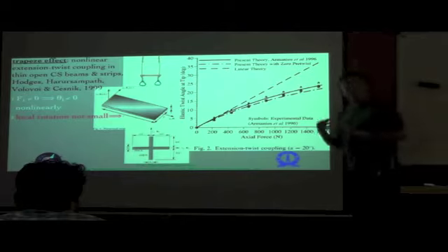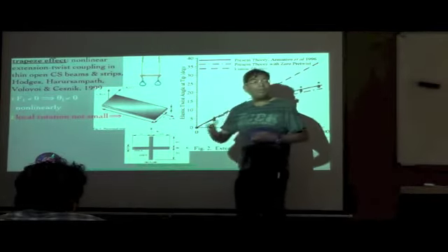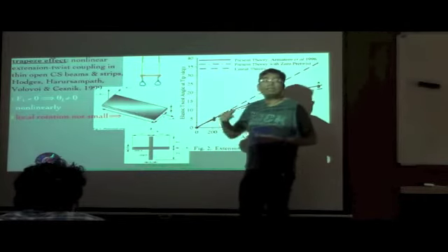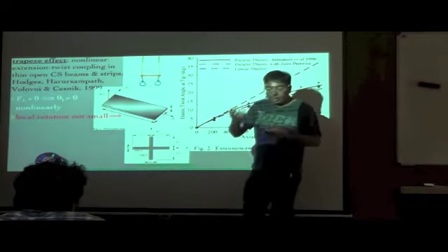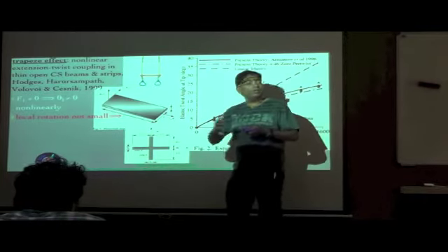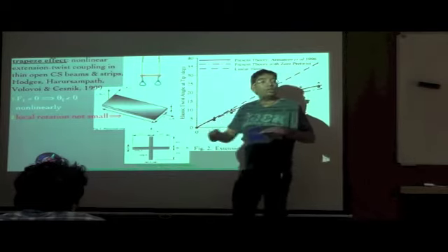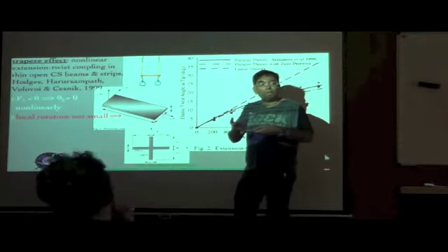Though W1 could have been there to a small extent as well, the primary or leading terms were W2 and W3, whereas here it is W1, or in other words out of plane warping. You know that torsion of non-circular cross sections will cause warping. Here of course you are applying an extension load, and that is resulting in a twist, which in turn is resulting in an out of plane warping.